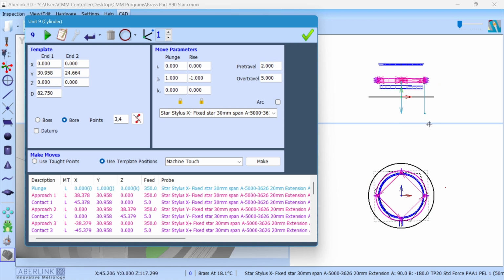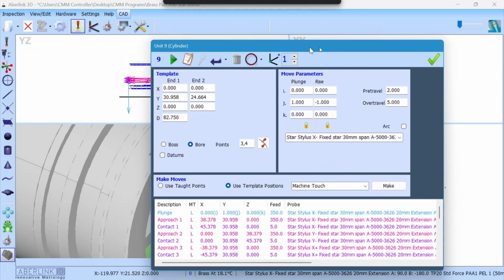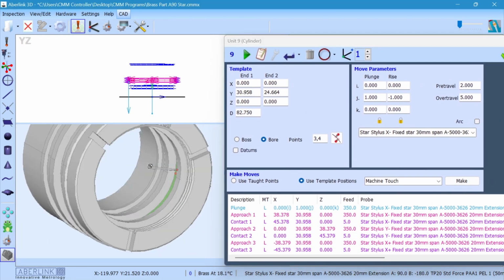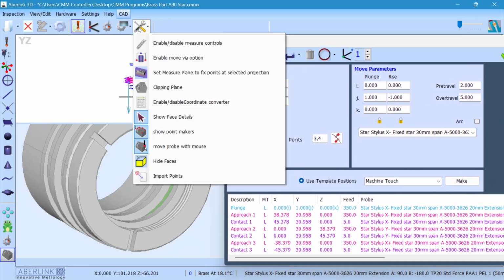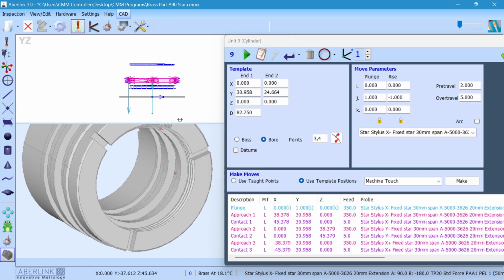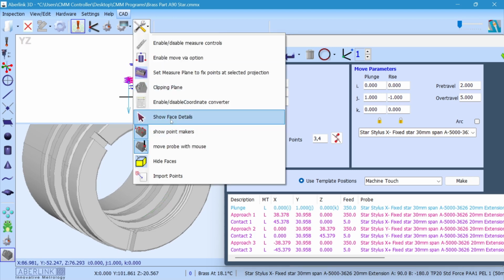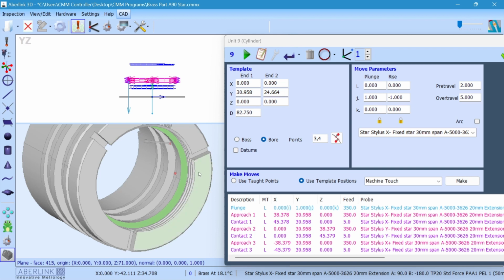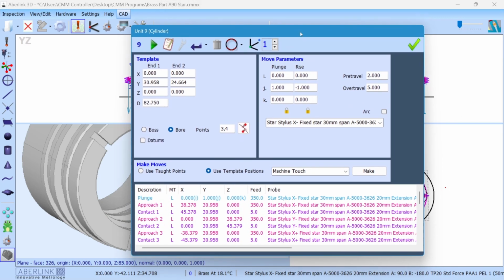front of the job. However, as per the previous exercise, the headache is that it's now going to drive directly to the start point, which is going to collide on this face. Potentially also this face, depending on the depth of the undercut. So how do we avoid that collision? Well, in this example, we're going to use move wires.